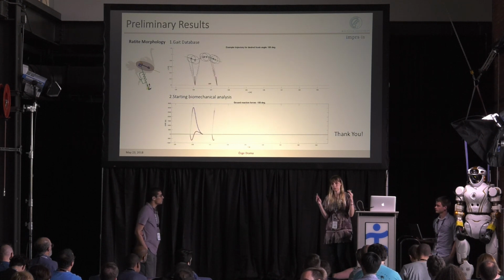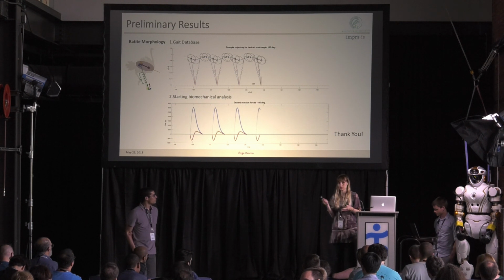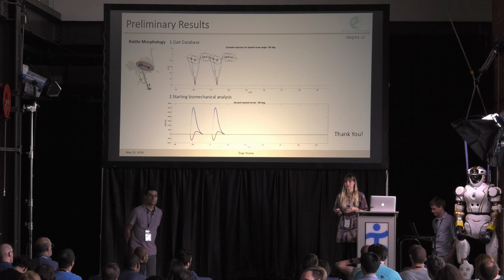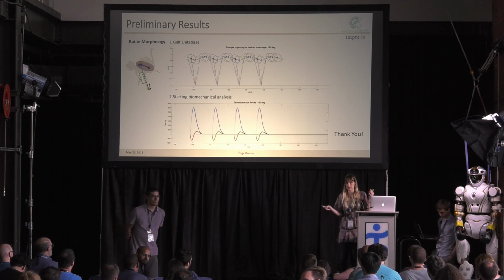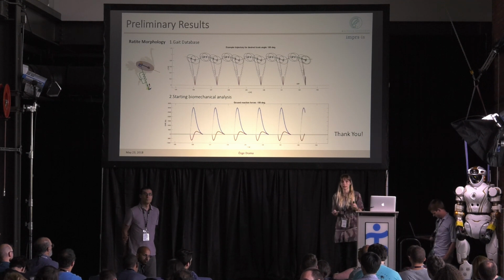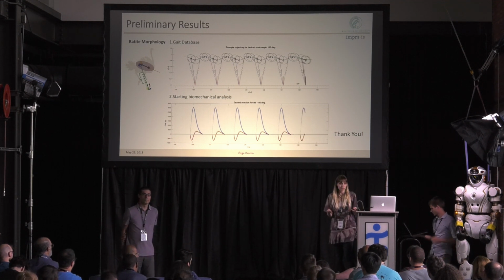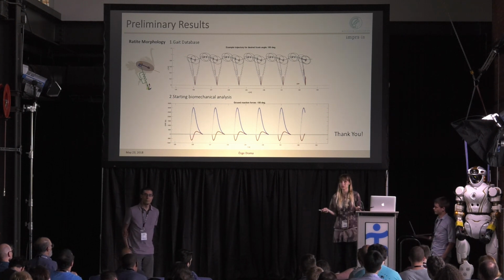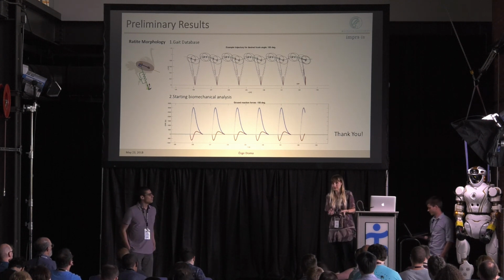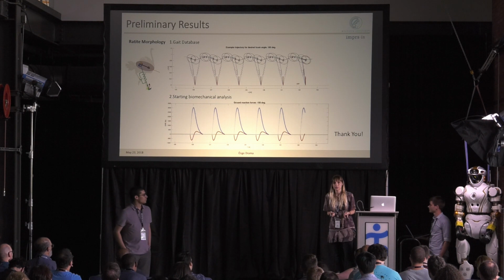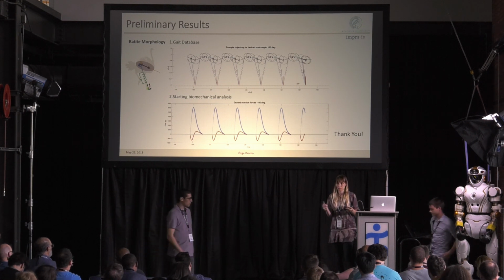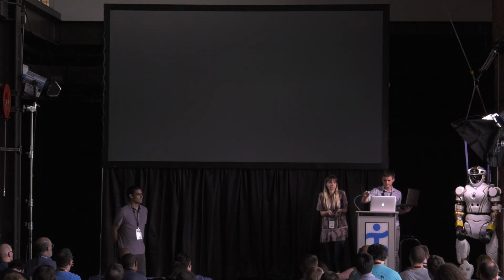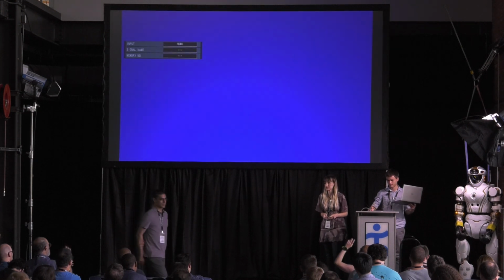Ground reaction forces pointing to a point which is higher than the center of mass is the virtual pivot point concept, I'm guessing, that you're referring to. There are a lot of discussions, and there is a hint in the data. For instance, when I look at the Guinea fowl data that we have, there are some steps which yield such behavior, but it's an ongoing investigation. Basically, whether it's a point or a trajectory or a region of attraction is also not that clear to me yet. So you can try to achieve it from the control side, basically saying, okay, I'm going to use another controller to yield such a behavior, for instance. It's an ongoing process. Thank you.